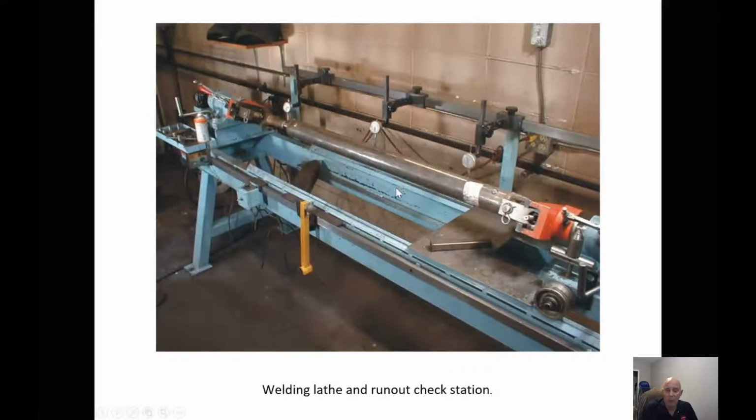Now, the other thing they want to do is make sure that once the drive line is all assembled and welded together, that we don't have runout. And we're going to use a dial indicator to check runout. There's a thing called TIR, total indicated runout. Anytime you're checking the total indicated runout of a drive shaft, you're going to use a dial indicator.